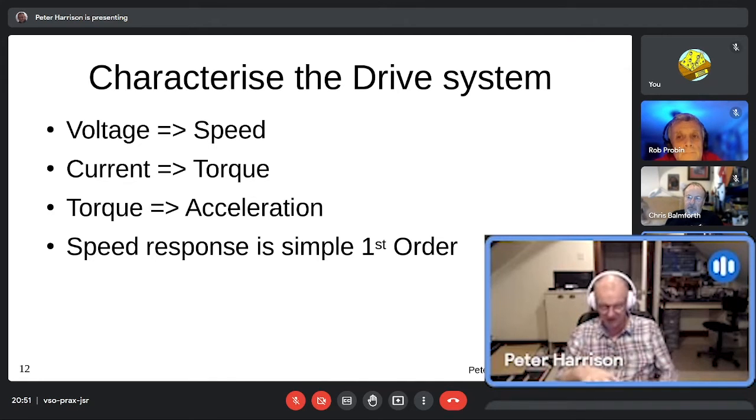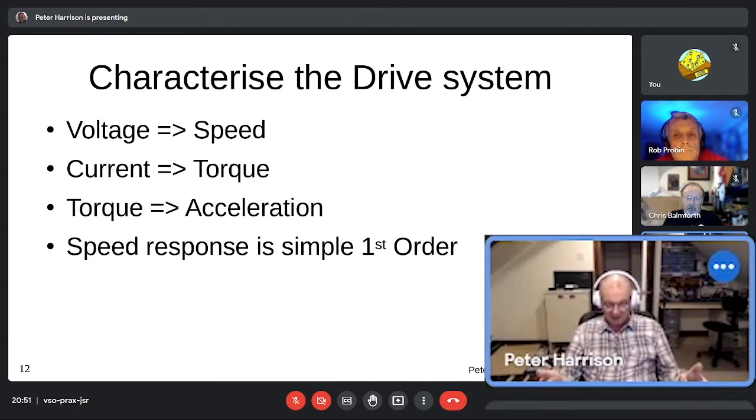Now, we're not going to do the whole maths of motors, but this is the simple way to look at it. So consider, for example, that you have a motor running, or a robot running along on the flat. You fed it with 4 volts and it's doing 1 meter per second. But then it encounters a hill and has to go up the hill. What's going to happen? Well, it'll slow down, okay? Because the voltage is constant, but the load has increased, so the speed will decrease.